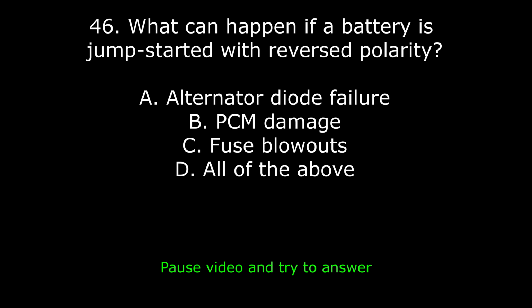47. When removing a cooling fan shroud, what precaution is necessary? A. Disconnect fan motor connector. B. Drain coolant. C. Disable ignition. D. Remove fuse box. Answer: A. Disconnect fan motor connector. Explanation: fan may start automatically. Unplug to prevent injury.